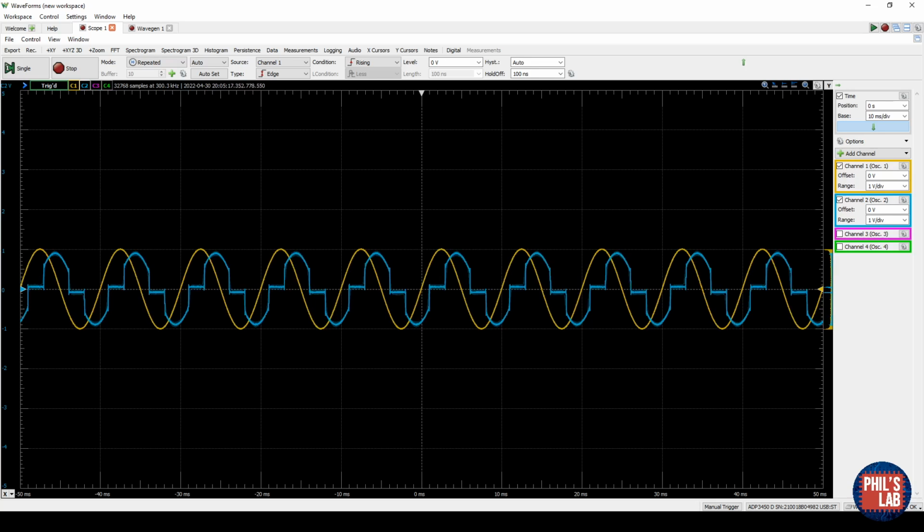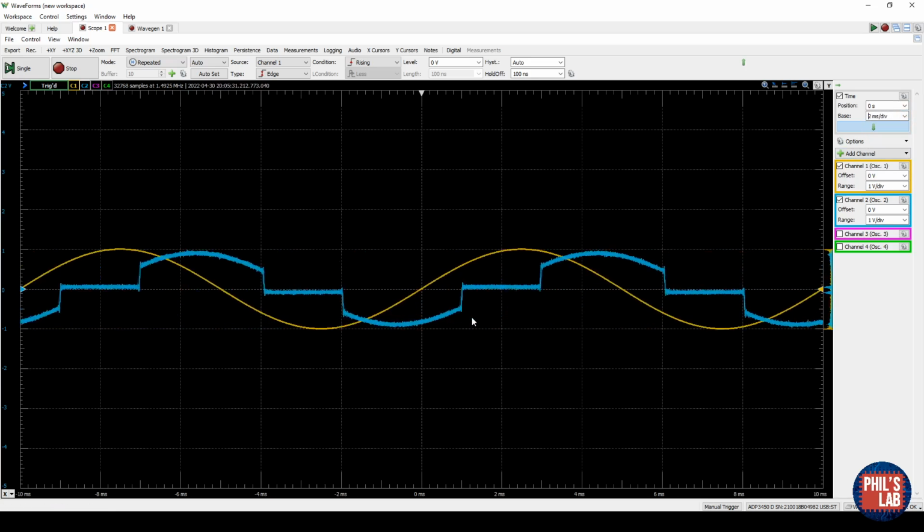Now I've moved it almost halfway, and you can see the rather nasty effects of this noise gate. It is doing what it's supposed to do for this very simple noise gate. If we change the time base and zoom in a bit, you can see it's doing exactly that. Below a certain value, the threshold seems to be around half a volt, a bit higher, 600 millivolts, it completely shuts out the signal, and as soon as the signal goes above this threshold, which is plus or minus 600 millivolts in this case, we let the signal pass.